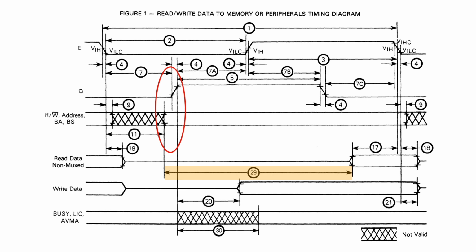Now, consider the AT28C64 EEPROM, like the one I'm going to be using for the fixed ROM. Those actually have an access time of 150 nanoseconds typically, which means there's not a lot of time to assert this chip select signal. I could give the EEPROM a bit more time by building the MRD clock stretching circuit that I briefly mentioned in the clock generator installment, but I want to avoid that if I can. I prefer to have predictable instruction timings, and so it's pretty clear that I'm going to need to pay careful attention to the propagation delay of the decoding circuitry.